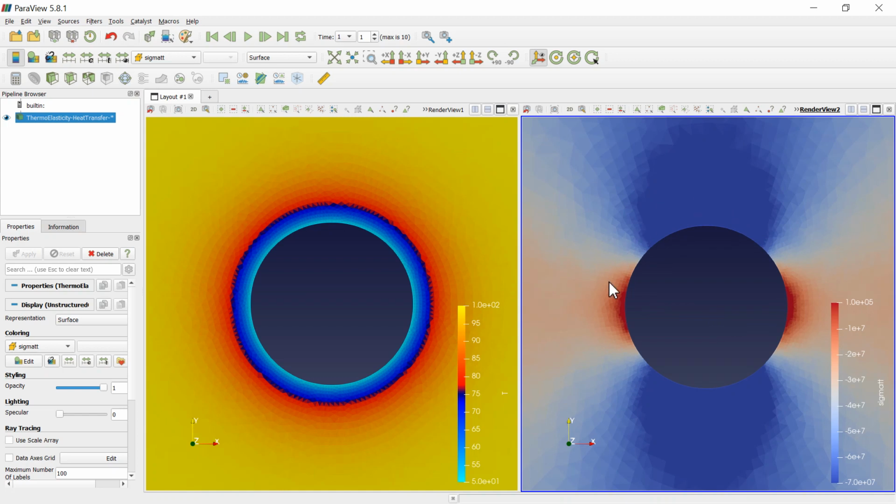That's because of the decreased stress in tangential direction, or the hoop stress, around the wellbore. And if I continue varying the temperature and showing the variation of the solution with time, stresses are going to get lower and lower around here until I reach the steady state condition.